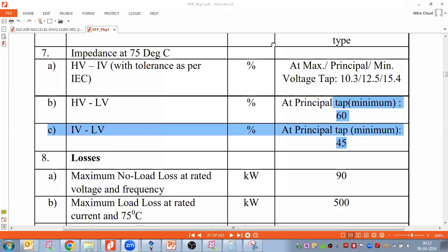If you need to compensate the reactive power, in that case you need to install a capacitor bank. Is there any criterion to match a 5 MVA transformer, how much reactive power? When I come to the capacitor bank sizing, at that moment we will do simulations, and then we will decide the capacitor bank sizing. Hold on, we have a topic on that.